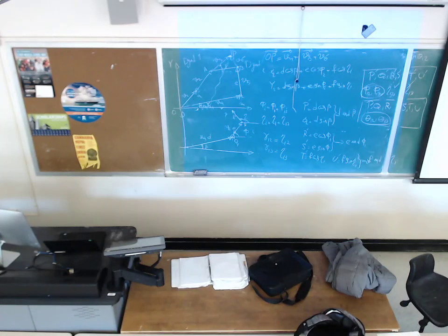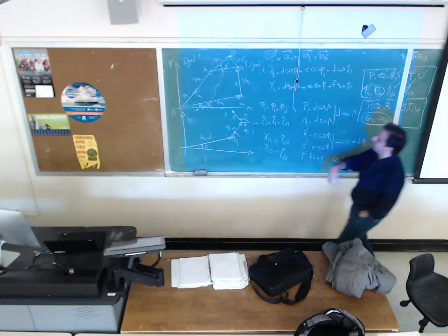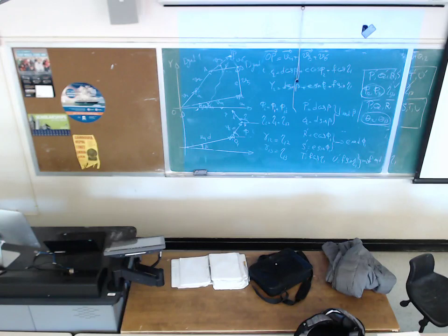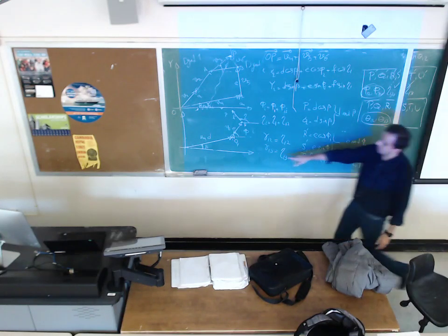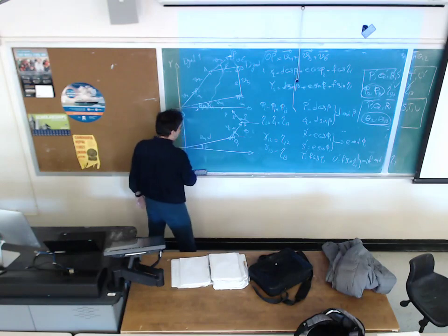So on the right hand side, the only tricky part was the value of eta_12 and eta_13, which is the same as gamma_12 and gamma_13. After you find D, E, and F with the corresponding angles, you can draw the mechanism.